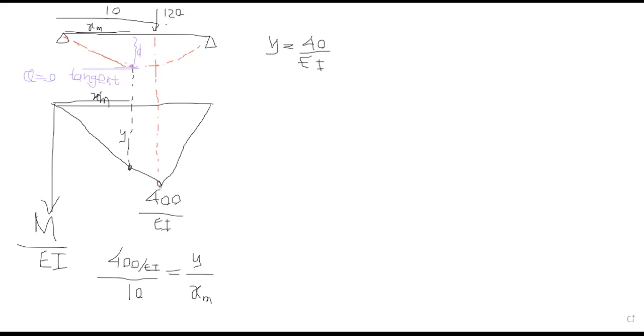So it's just a matter of taking it as XM, right? It's a common term. So still the maximum bending moment occurs underneath the load, but deflection is not, right? It's somewhere else. Maybe it's closer to this load, right? Maybe several millimeters away. We can't tell. We don't know, right?